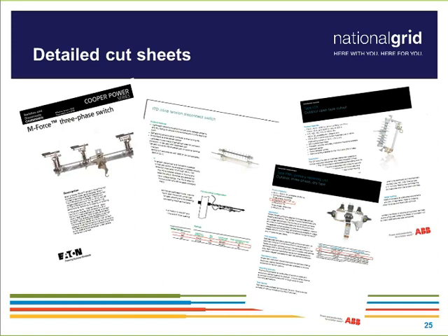So with the cut sheet packages, if you're using a gang-operated three-phase disconnect switch, if you're using hook-stick type fuses where you have a fuse and fuse holder, or if you're using a recloser or a circuit breaker, some kind of a shunt trip, the transformer, reactors and resistors, all those pieces of equipment have cut sheets, and they all tell a story. They all have the parameters that we would be interested in order to evaluate the design. So having those cut sheets submitted in a package